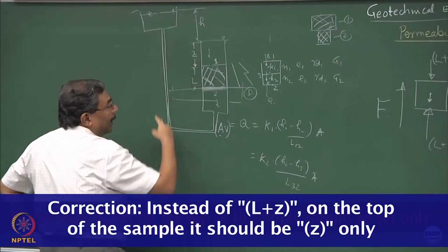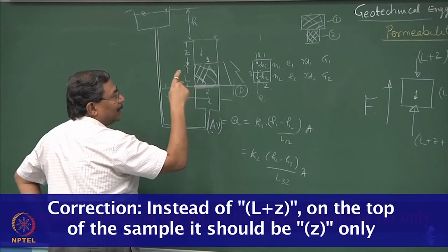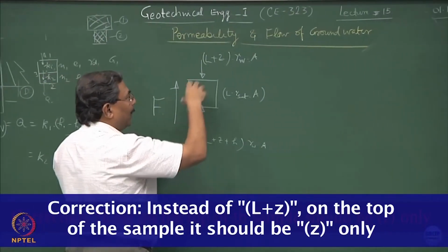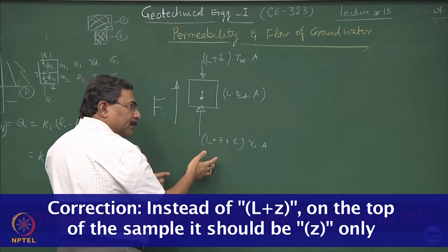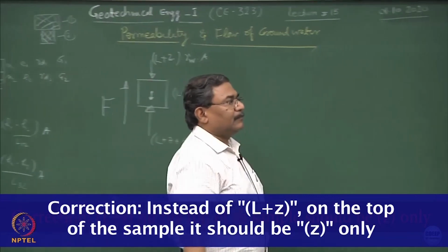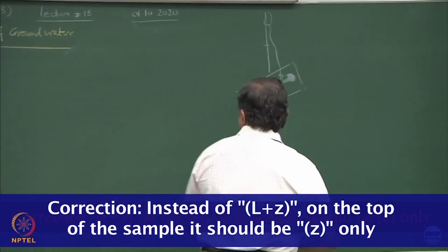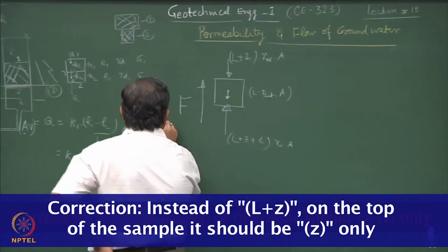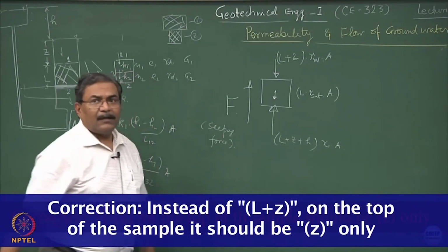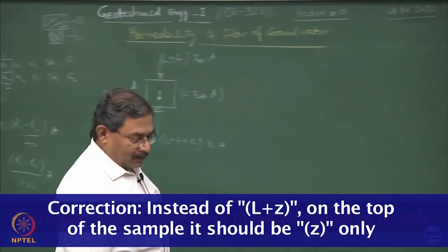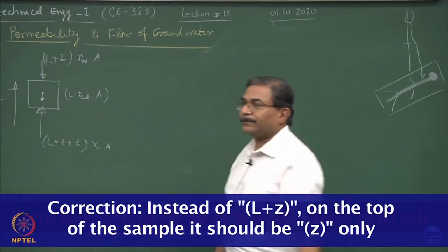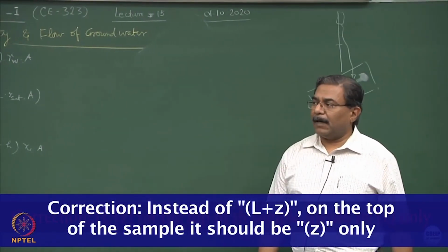Because the entire pressure head and elevation head is acting at this point. Clear? So truly speaking, what's happening? You have 1, 2, 3 forces and they are being balanced by F. And this is what is known as seepage force. That video clipping was regarding what? Quicksand. So we are going to create the quicksand condition. How?